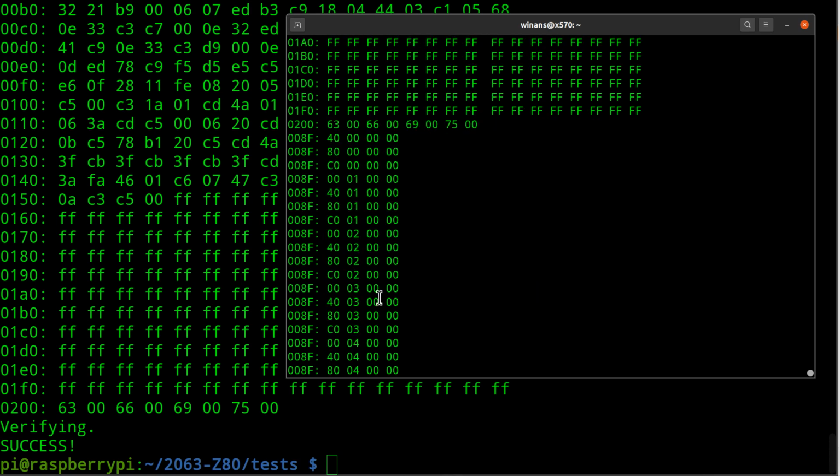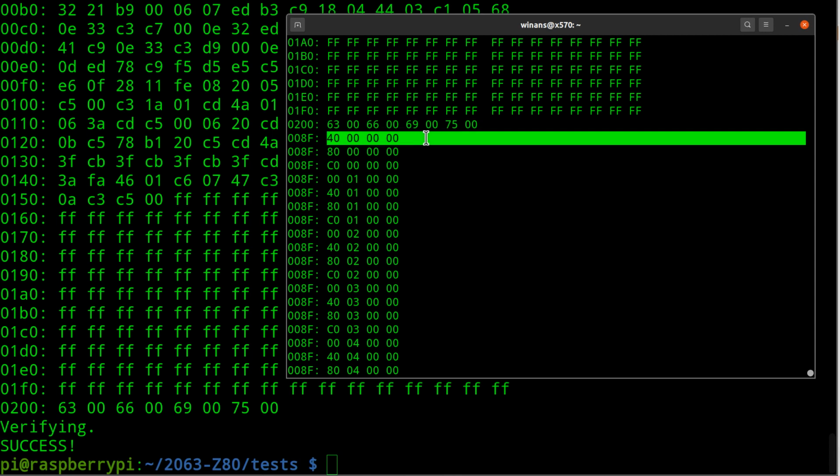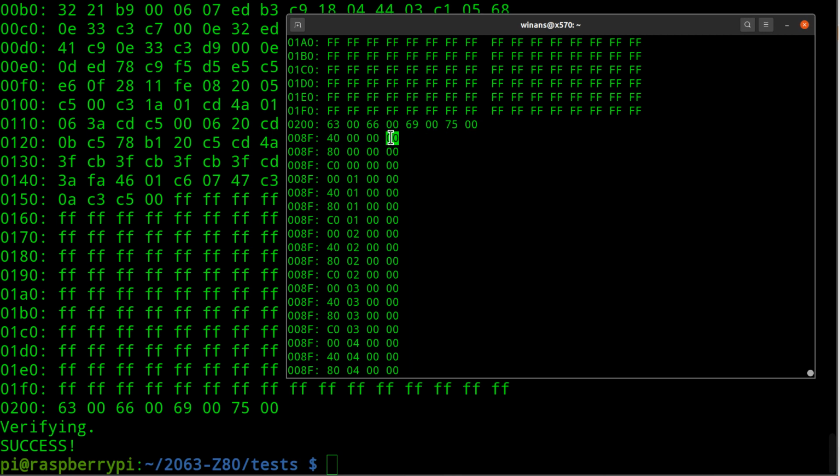Down here, once this thing boots up, it's printing out its uptime. Remember, it only prints the hex dump when the value is a multiple of hex 40. And because it's little endian, this is the least significant byte. So you might say the value of the uptime counter at this time when it printed it out here is 00000040. And it goes to 00000080, 000000C0. These are all multiples of 4.